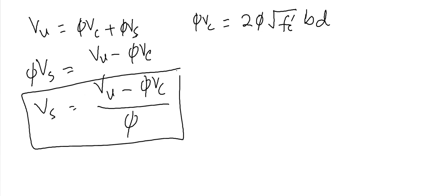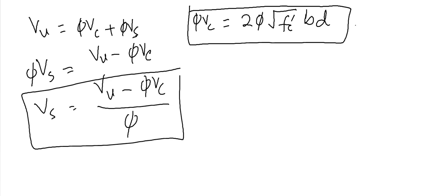Again, we need to use this equation somewhere when we calculate the spacing. So hopefully you understood this equation. This is the capacity of plain concrete, and this value is based on testing or experience, so there is no scientific derivation, and this is just mathematics. Total design shear force, concrete will take some, steel will take some. Then if I rearrange, the contribution of steel in shear force is this equation. We need this equation. So remember these two equations.